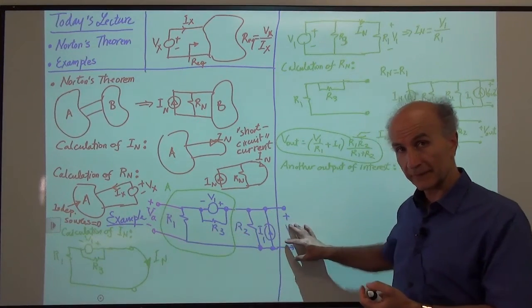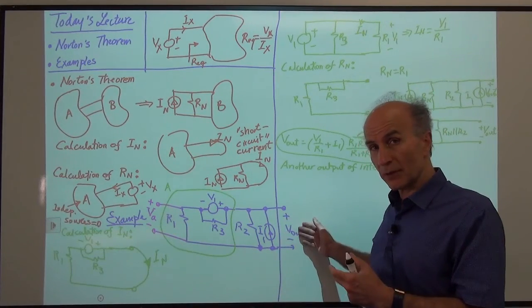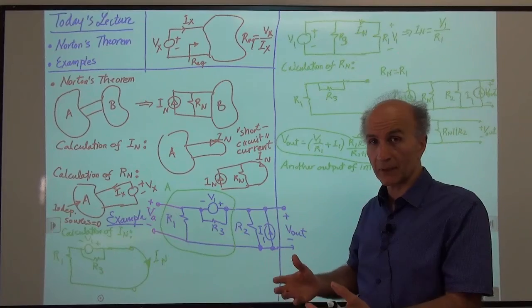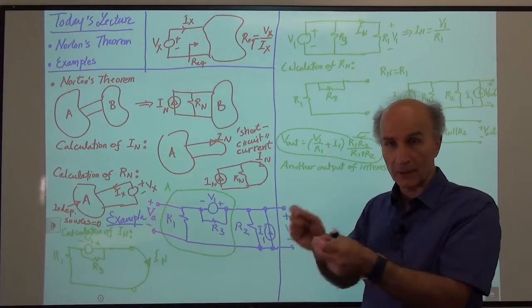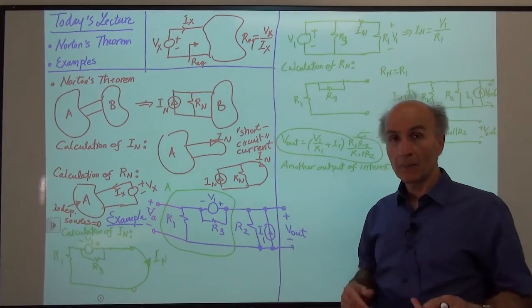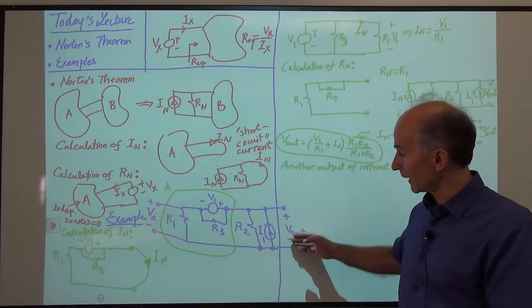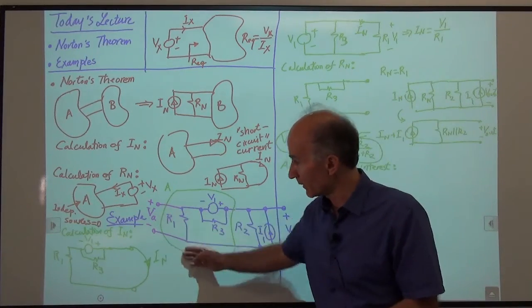It's outside. Now, it's not a big deal if you lose the quantity of interest, as long as you can solve the circuit, because eventually all of these numbers are related to each other, right? This voltage and that current, etc. So if you solve the circuit, that's fine, but it's preferable not to include the output of interest in this section A.